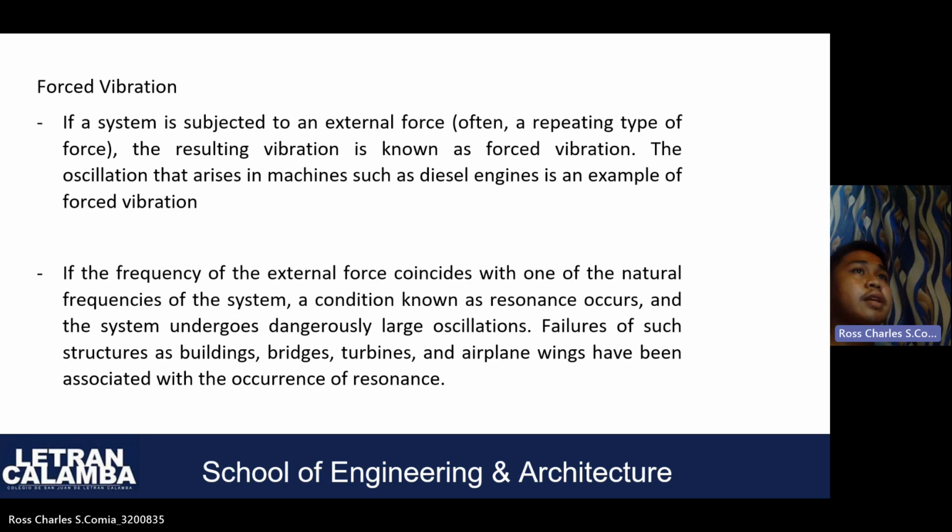The oscillation that arises in machines such as diesel engines is an example of forced vibration. If the frequency of the external force coincides with one of the natural frequencies of the system, a condition known as resonance occurs, and the system undergoes dangerously large oscillations. Failures of structures such as buildings, bridges, turbines and airplane wings have been associated with the occurrence of resonance.